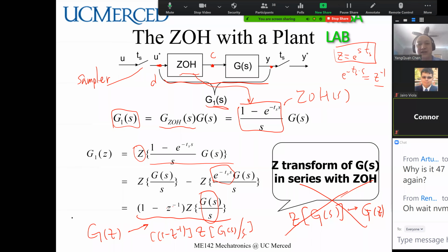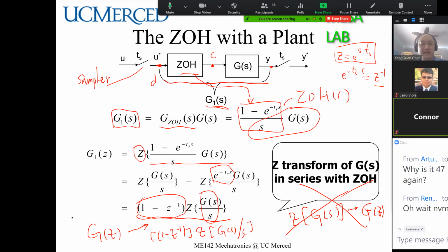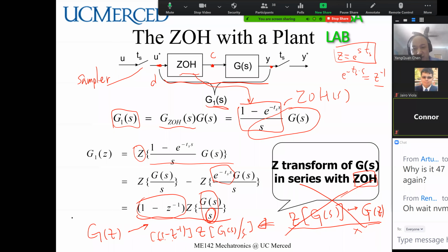So the whole thing is 1 minus Z to the minus 1, but you need to combine these two as a system, okay? So you basically have the 1 over S, like an integrator, cascaded with G of S. That's the correct way to do it. If you simply take G of S to get a G(Z), that's wrong. Don't do that, because you have a ZOH, you cannot ignore it. So the correct one you should do is this way: 1 minus Z to the minus 1, then you take the Z transform of G of S divided by S. That's the correct way to do it, okay?